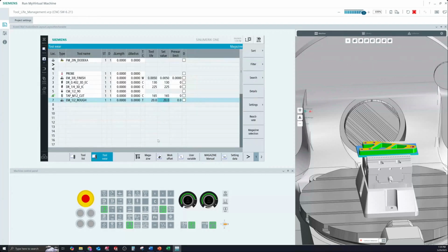So that's how we can find our tool life from actual data from the machine. Now we're not having to rely on our operator to write down the numbers like, hey, when you're running these, write this down. And every time you change this tool out, write down how many parts you got or write down how many minutes it cut. That's never going to go over well. I can promise you, I've been there several times. So by doing this, the only thing I'm basically putting in his responsibility would be to, when this tool is changed, to come here and reactivate it.